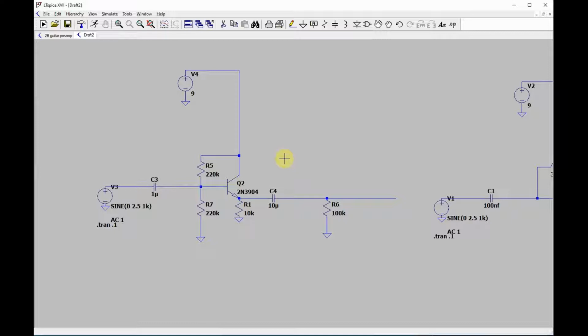So this is a really common configuration, and I'd say this is a rule of thumb, if you will, that if you want to find how big of a resistor you should use here compared to there, usually you take this number and multiply by 10 for an HFE of 100, and then you double it, you're right at 200K. That's a rule I don't infrequently use: multiply this by 10 and double, as a rule of thumb for the ratio of here to here. That works pretty well usually.